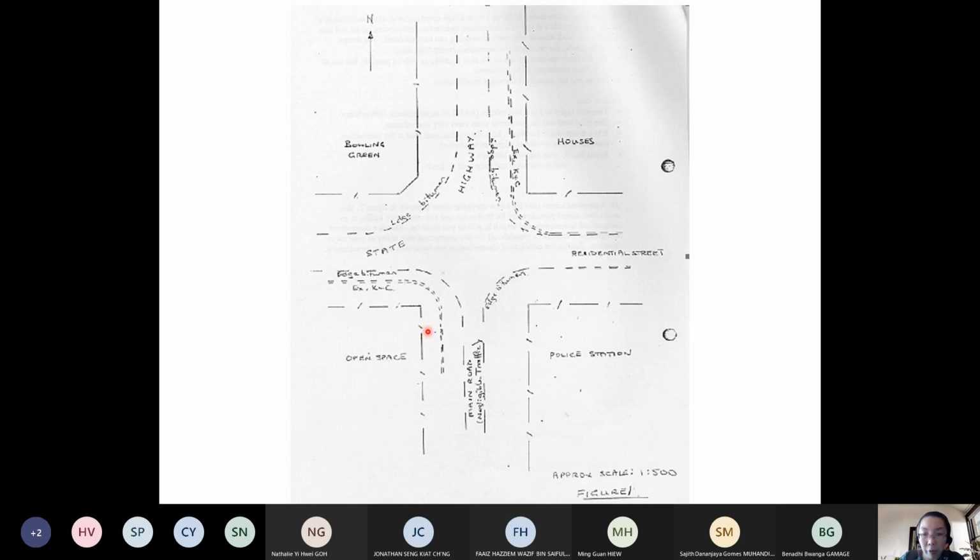What this means is that if you are to extend the road, you have this much space before you reach the existing curb and channel. If you want to further expand it, you will need to remove the existing curb and channel. Okay, so if you were to draw it out, because there is a scale given at the bottom, then you have to draw proper realignment, proper signage, proper markings. All right. Now let's get back to the points in the question.